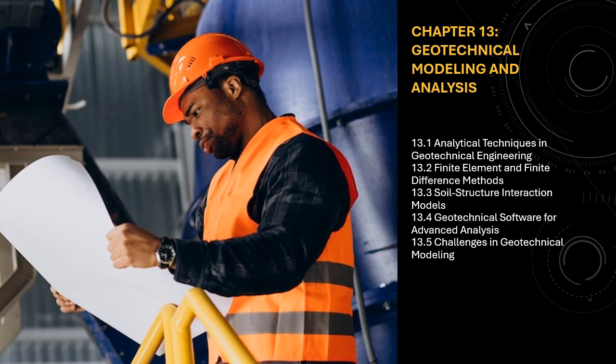13.1.2.4 Discrete Element Method, DEM. The discrete element method is used to simulate the behavior of granular materials, such as sands and gravels, which are highly sensitive to particle interactions. DEM models soil as a collection of particles or blocks, and it can simulate soil behavior under various load conditions, such as shearing, compaction, or shear band formation.